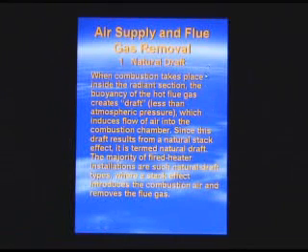So let's talk about natural draft first. Basically, if we have a natural draft heater, the stack draft is what is pulling the air in through the heater. There is some motive force given by the burners, which act like an eductor. So the fuel gas at pressure will motivate the air coming into the combustion area.